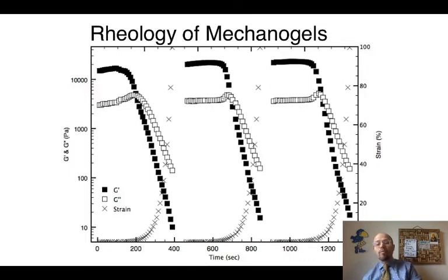And this is why it's so important, right? We don't want fuel that's been spilled outside to flow. We want to trap it, transport it, and then do whatever we want with it. Make it flow if you need. And so the neat thing here is that we started with a solid. We ramp up the strain, so we strain it more and more until it turns into a liquid. And then if we let go for a little bit, about 60 seconds in between, we can see that the solid comes back. And then we break it up again, we turn it into a liquid, we let it sit, and it resets and becomes even a little bit stronger, as you can see.